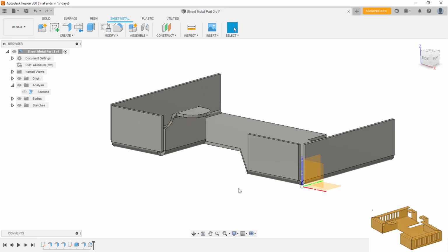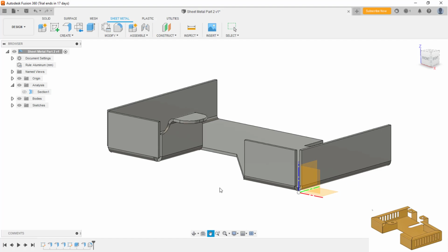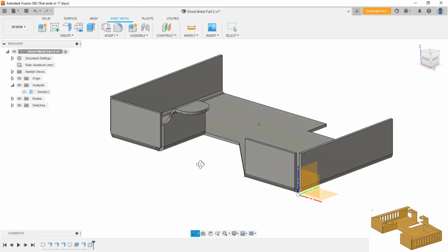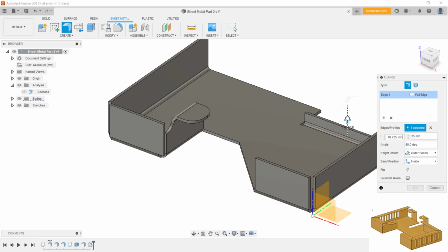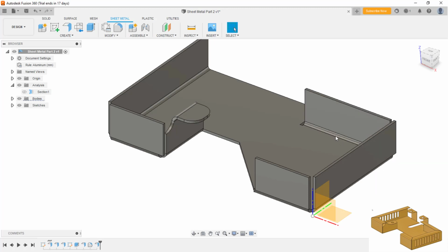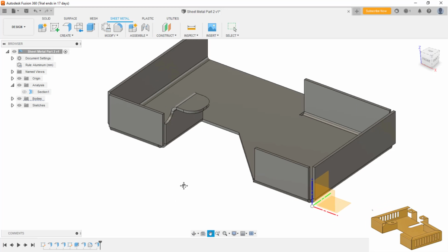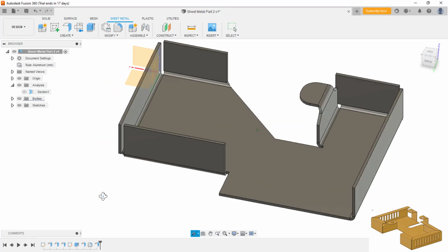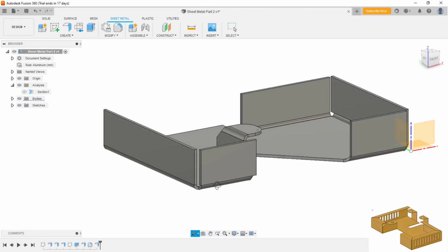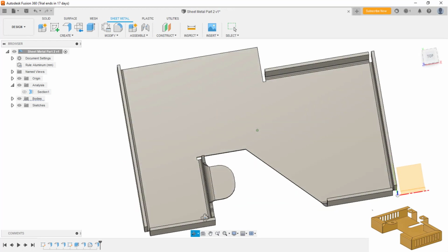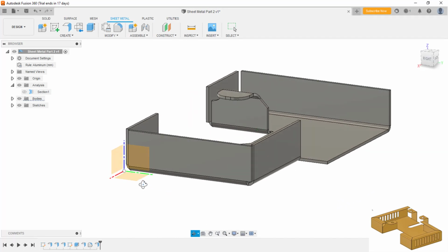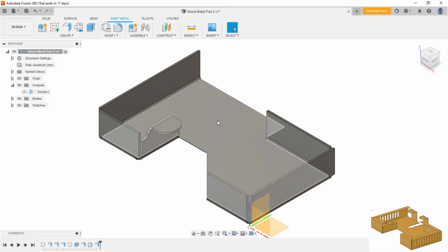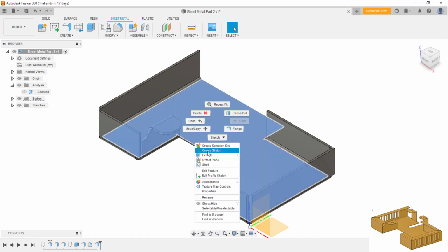Next thing, I need the slot at the center, as you could see, which we have created here. So first I'll extend this portion up to a certain distance. It is the same thing as we have drawn for all the edge flanges up to 30. You can just do the same thing. Now you could see this is fine. Yeah, so now on this face I'll create the slot cut first.